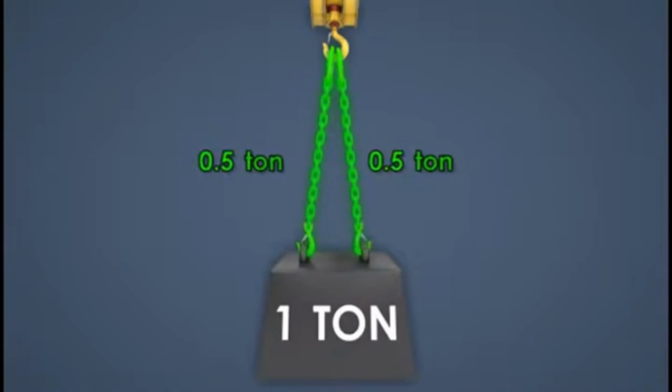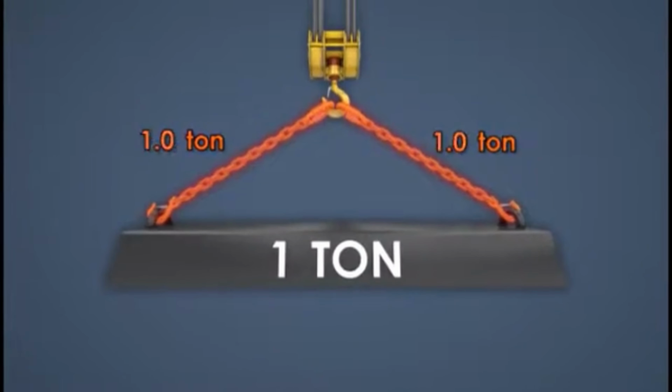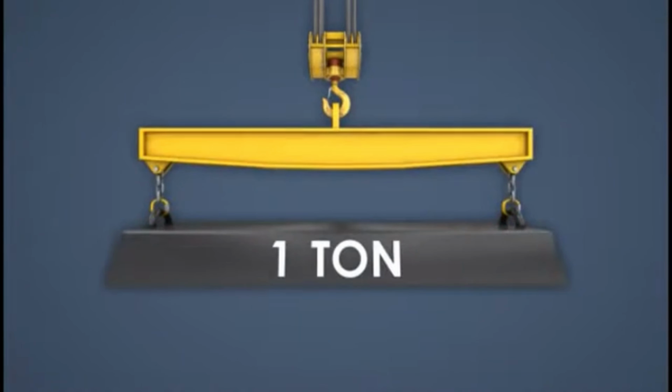A 1-ton load can produce several tons of stress on each sling arm at a low sling angle. This is why spreader and lifting beams are used for longer loads. They make the sling legs more vertical.